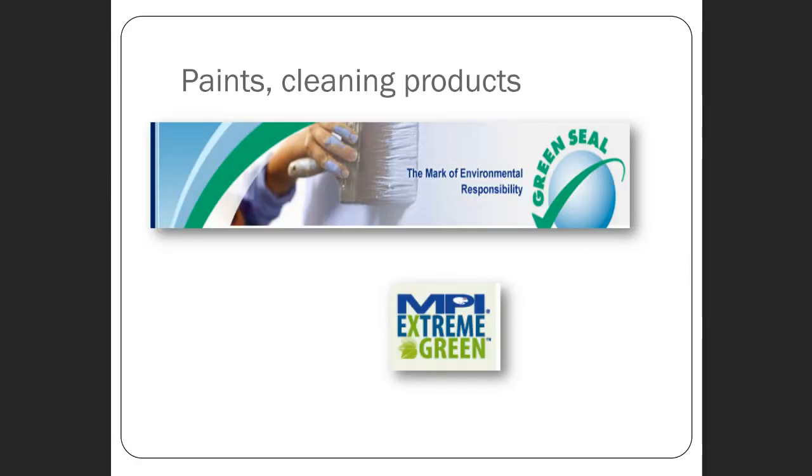Here are two rating systems for paints and cleaning products. Again, if we're looking for low VOC paints, you could say paints shall be low VOC and shall bear the Green Seal or the MPI mark, right? Then we know what we're getting.